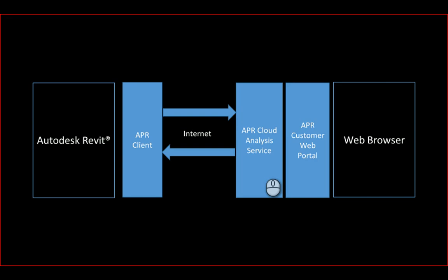The takeaway from this presentation is that managing a code compliance strategy for a building is made easier and more explainable by BIM tools and SMARTreview APR. So APR is an add-in to the Autodesk Revit to guide the designer in producing a building design. Our software helps the designer to add relevant information to the BIM and then sends information to a cloud service that checks the BIM against rules for compliance. The results are reported back to the designer as advice embedded within the building code and as annotations on the BIM.